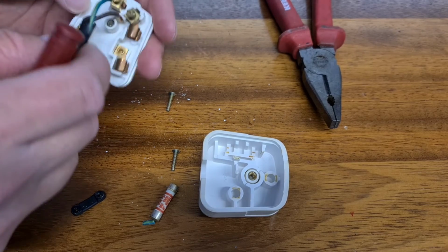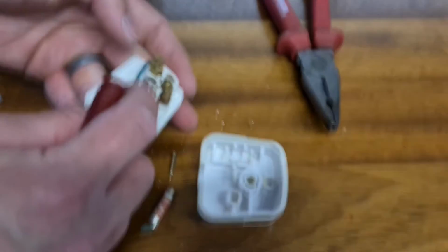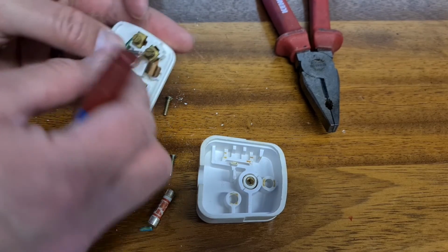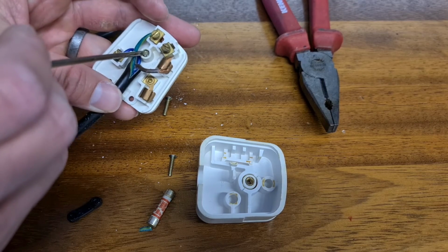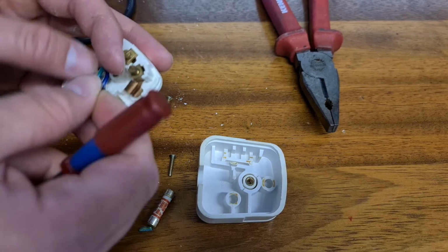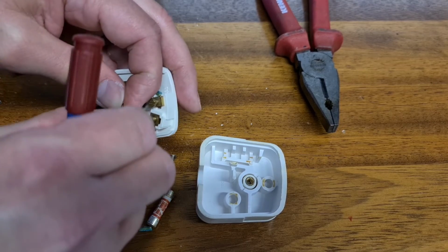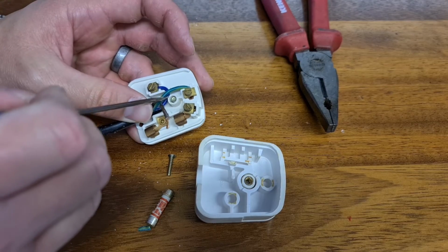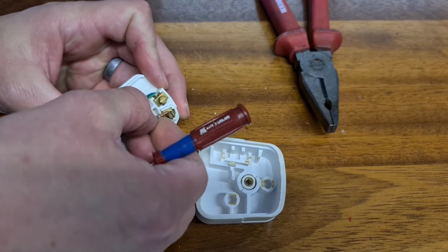Now the final stage is we must make sure that these cables are twisted around the little tiny section there where the actual main plug screw goes, so it doesn't foul that area, so you can actually get the plug back together. Some people find when they do this that they foul that and then everything looks right, but they just can't get the case to go back on.